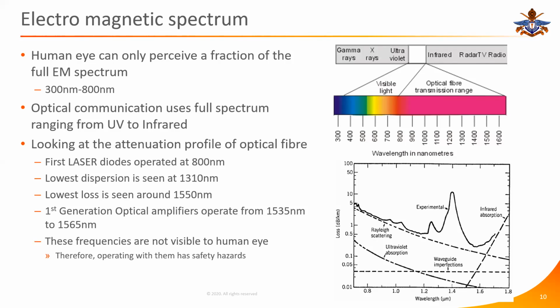I am pretty sure the signal will stay. You send 2 volts peak to peak, and up to a certain frequency, you will see 2 volts peak to peak on the oscilloscope. But after a certain frequency point, the amplitude you see in the oscilloscope will start to go down. And that is not because there is a problem with the oscilloscope, but the coaxial cable will start to attenuate that signal, take the energy away. So at certain frequencies, coaxial cables will have this problem.